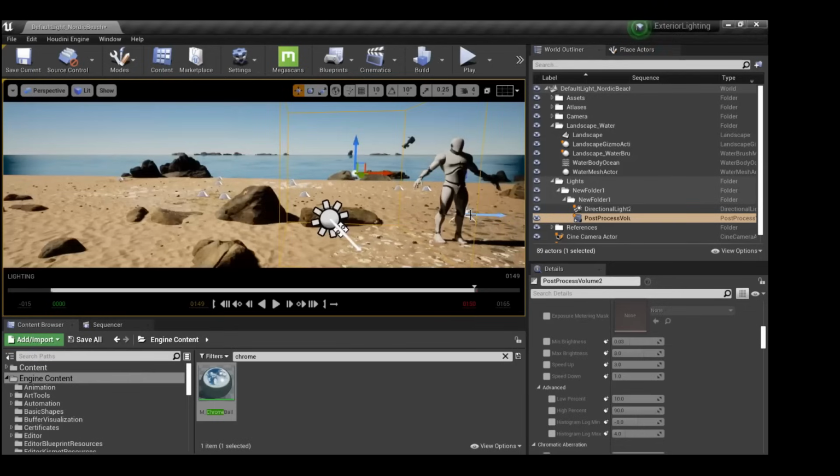Yes. And if I'm going to use a custom HDRI, and I'm using a directional light, so directional light is our sun, basically. So I need to connect that sun to my HDRI sun, basically, to achieve that realistic effect of the shadows and lights, right? And if I rotate the HDRI further, then I again need to move my directional light. Yes. So if I don't want that, I need to write the blueprint. It is very easy to work. Yes. And I don't like blueprints, basically. Okay, got it.